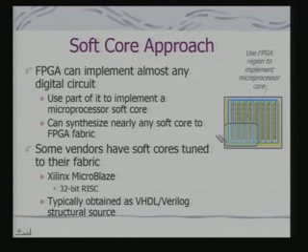And that gets interfaced here. So, once we get one particular configuration, what are we getting? We are getting an instance of the platform. The platform as such, if I start with 8051 as a VHDL, can implement a variant of your microcontroller family of 8051. Which particular instance you implement will be dictated by your requirement.